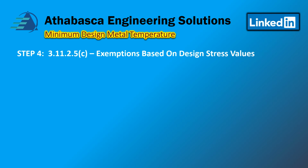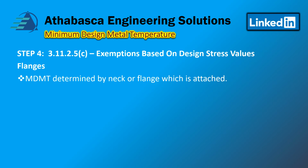So we're going to move on to exemptions on the design stress values. We're looking at flanges. The MDMT is determined by the neck or flange which is attached, okay? And the bolt-up condition is not considered in the MDMT evaluation.